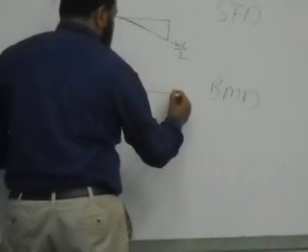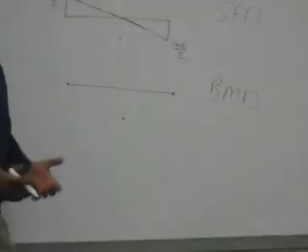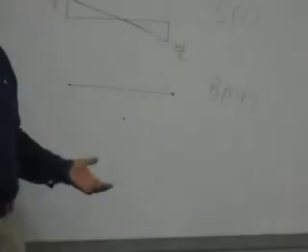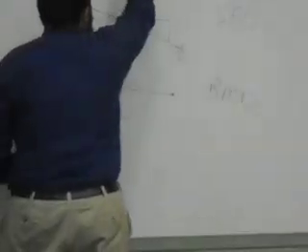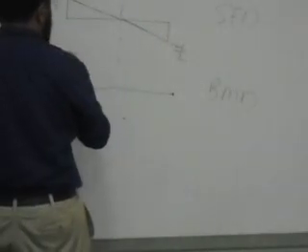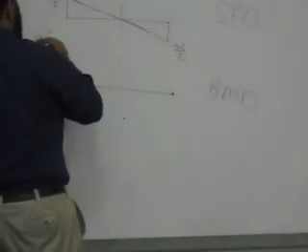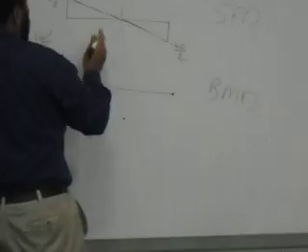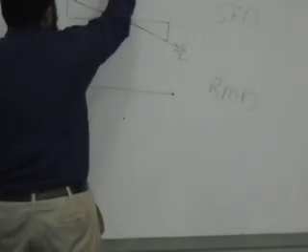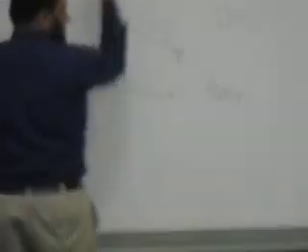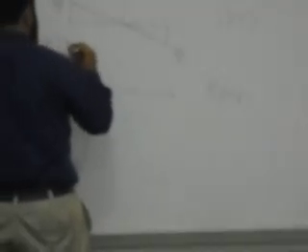So I have 3 points to draw a curve. To draw a parabola, you only need 3 points. So the first one, the last one, the middle one. How should I calculate it? One of two ways. Either take a section in the middle and look there. So in this section, my bending moment will be WL over 2, the reaction, times the distance, which is L over 2. So WL over 2 times L over 2.